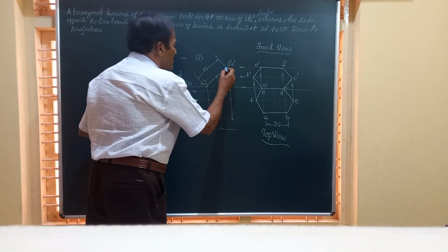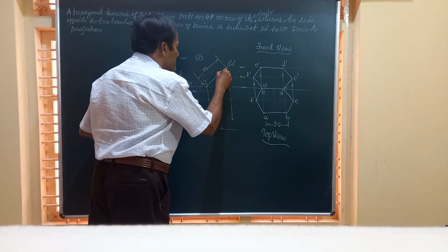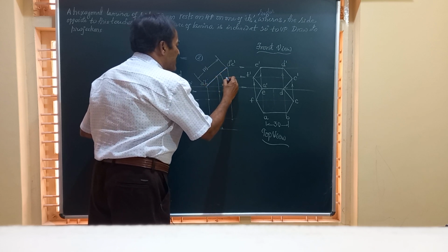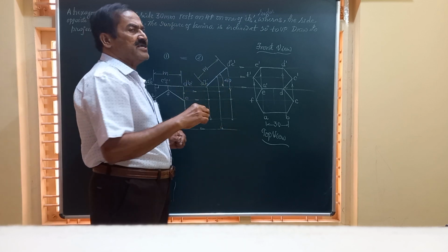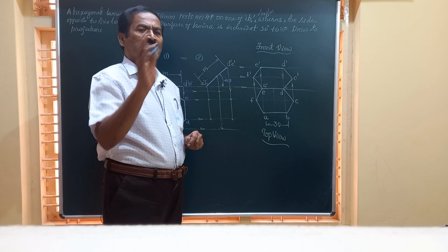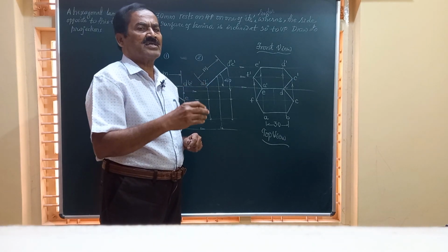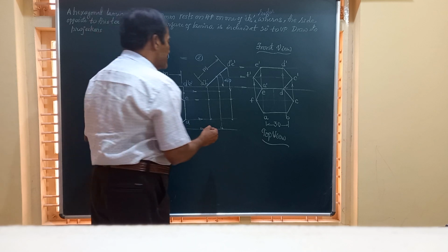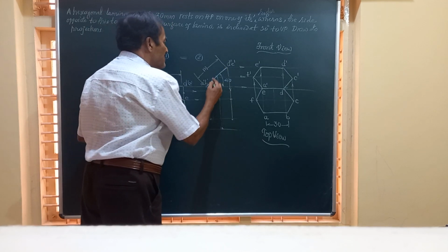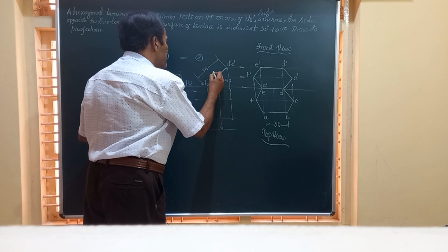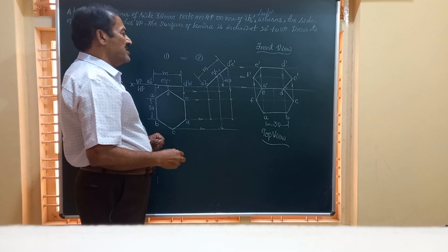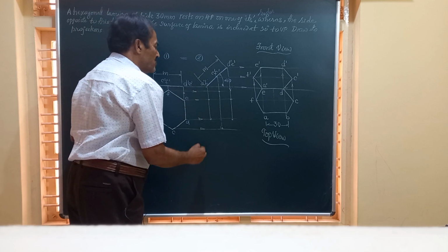Now friends, I am going to draw a line here at an angle theta equal to 40 degrees, and obviously when theta is 40, the angle made by the surface with the VP will be 90 minus 40, that will come automatically 50. Now corresponding to this front view, we are going to obtain what is called the top view. That is possible by projecting all these lines one by one.